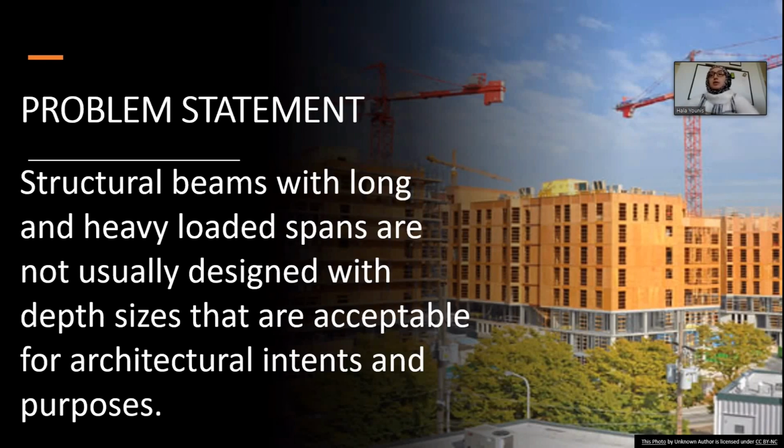Architects and engineers are finding structural timber beams with long span, longer than 7 meters, and supporting residential loads of, for example, 1.5 kilopascal are not serviceable enough within 300 millimeter depth floor space.